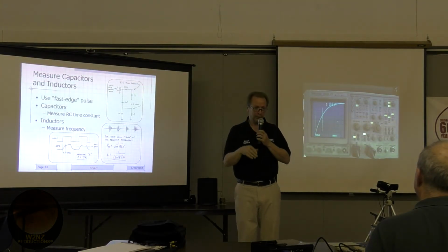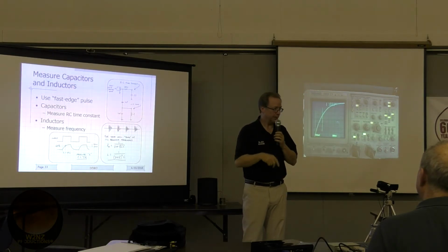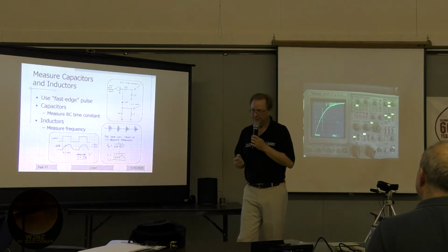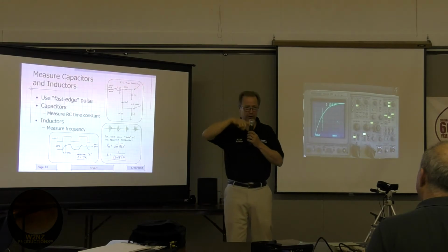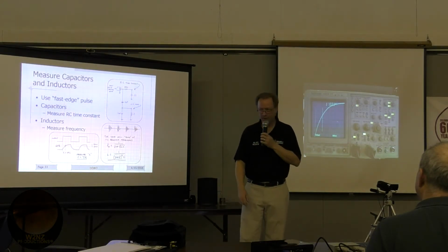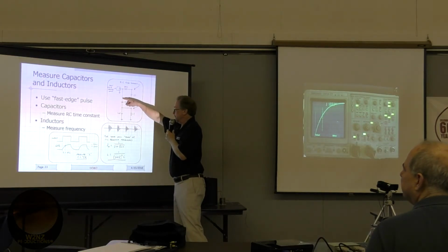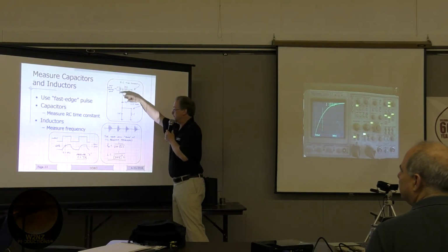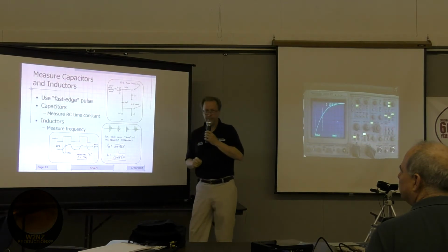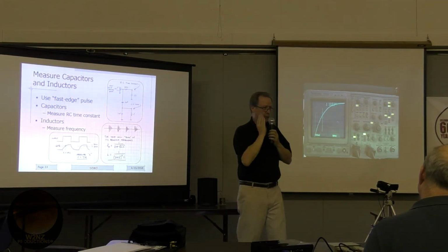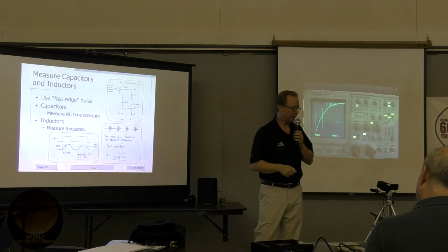It's got a resonant frequency where it's going to have a high impedance. And if you bang on it, like ringing a bell, you essentially will get a ringing voltage that will come out of it. So what we're going to do is send that high frequency pulse, that high speed pulse, fast edge, to a very small capacitor. So I'm only coupling the high frequency energy. I'm going to whack it with a hammer, basically.